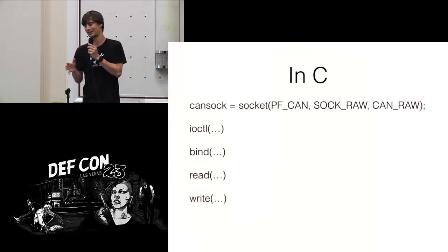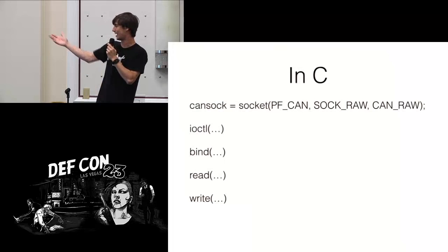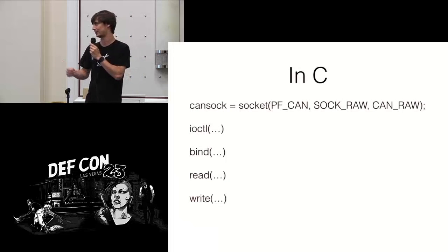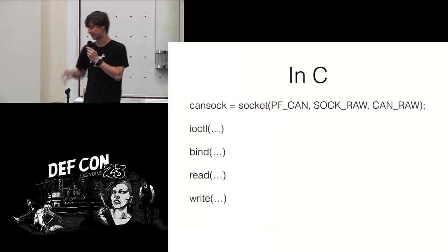Its support is kind of odd, it seems, but it's getting there. So once you have that socket, you can do everything you'd expect. You can call ioctl to set up, in some cases, bit rates, but at the very least set the address of it. You can bind to it, and then you can do reads and writes, and you can set socket options to block or not block or timeout, all those things.